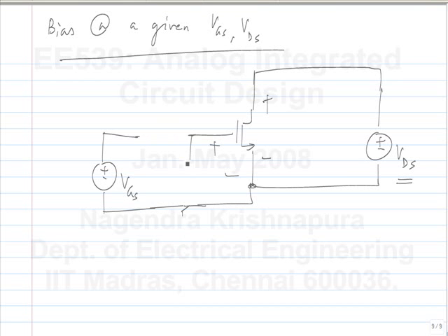So the alternative was if series doesn't work, you put it in parallel, right? This is what you wanted, or you wanted a capacitor also here? Okay. So what will this do? Capacitor. So where will the current flow? Yeah, it will be shorted. Inductor in series with VGS. Okay, perfect. So we can connect an inductor or a resistor because there is no DC flowing through it. We can safely connect a resistor also, right?